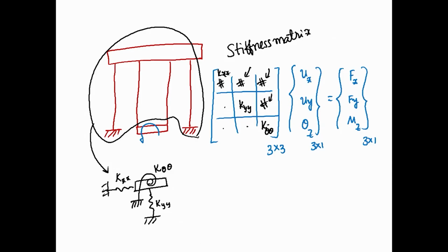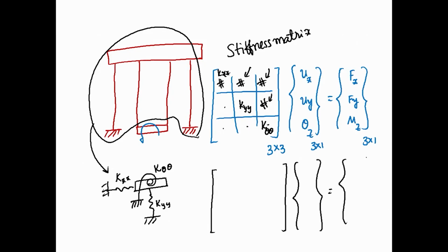We can get that using a finite element analysis code, which is what we will do now. The way we will do it is to construct what we call the compliance matrix, which is the inverse of this, meaning what this will do is it will try to relate the inverse of the stiffness matrix.